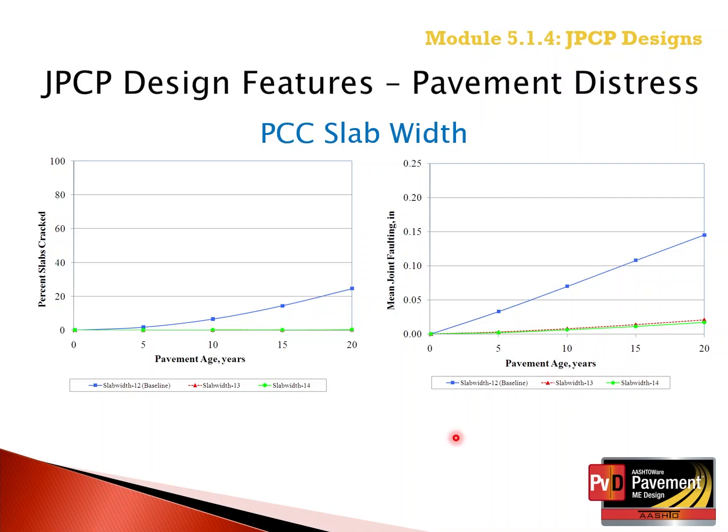Some in the industry, in fact, have recommended that 13 feet be the maximum width of the widened concrete slab. So just as a cautionary note, the longitudinal cracking of widened slabs was not specifically calibrated during the global calibration process.